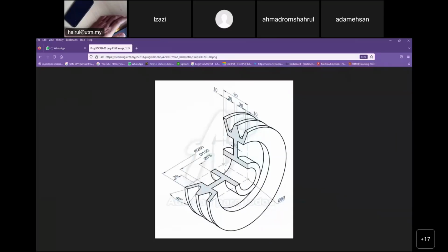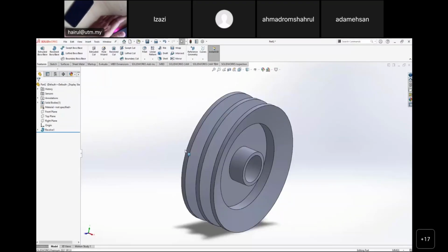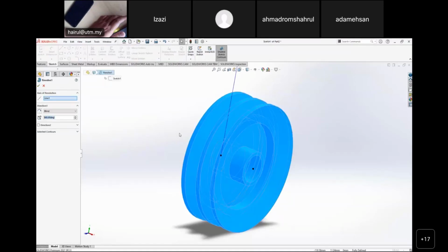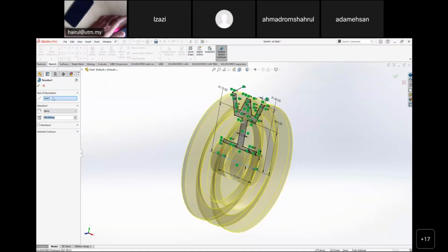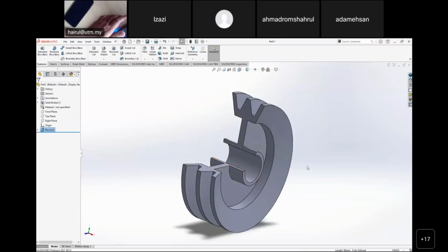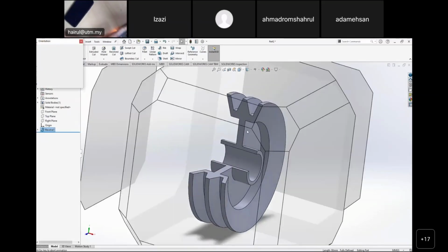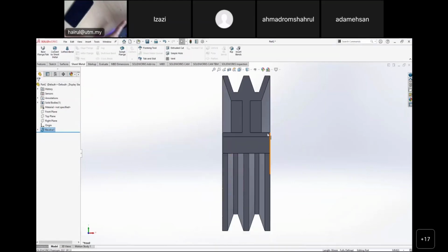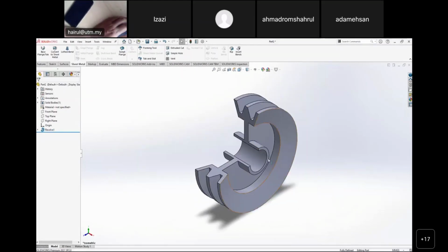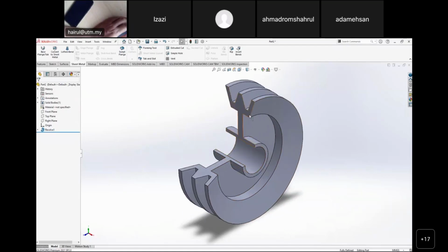But sir, the diagram shows like the cup half portion, can you show it like that? You can revolve in this direction. If I clear everything, for the axis of revolution I have to select the center line. That will be my axis. I want to go for 270 degrees. But mine is in that direction, so I can go to reverse direction. Reverse. I can produce it like that. This is the revolve 270 degrees in isometric mode.